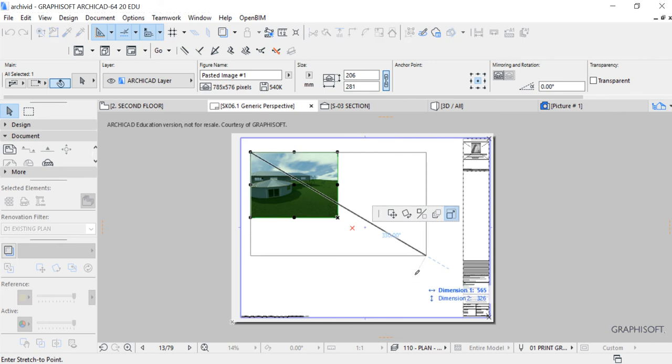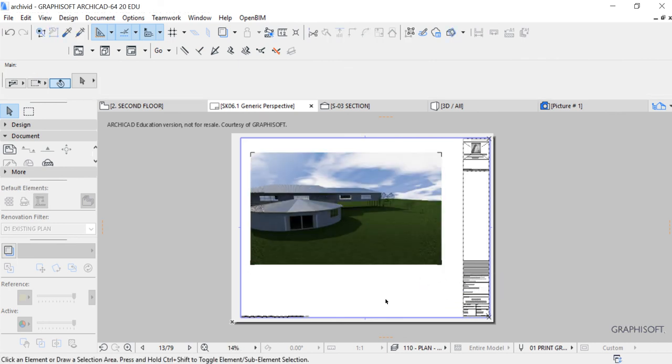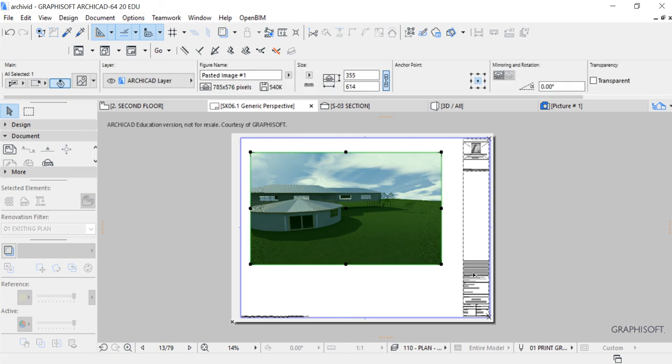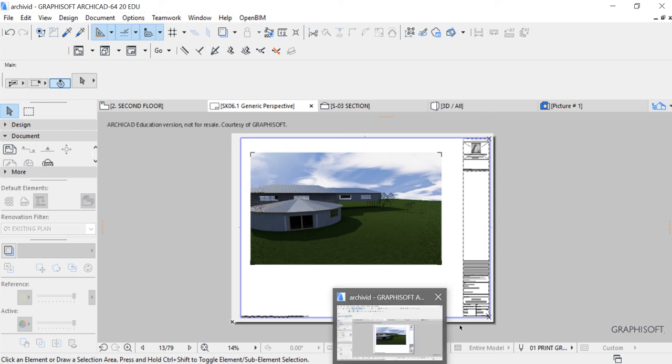And now this is a drawing. You can't change anything on this anymore because you've actually made it look real. So you might even put 4 different renders or something. Once again, save it as a PDF and you'll be able to print that to scale. All right, so obviously the 3D is not quite to scale, but it's pretty close.